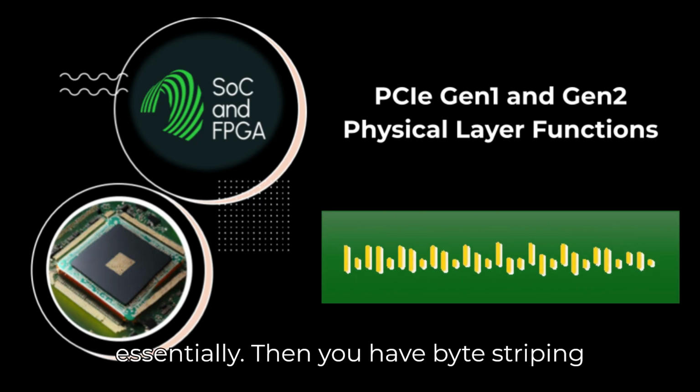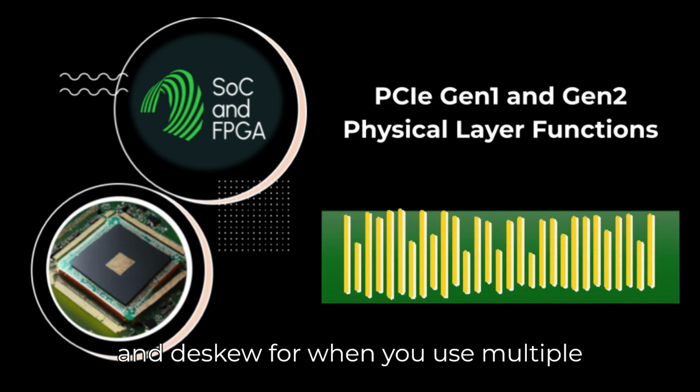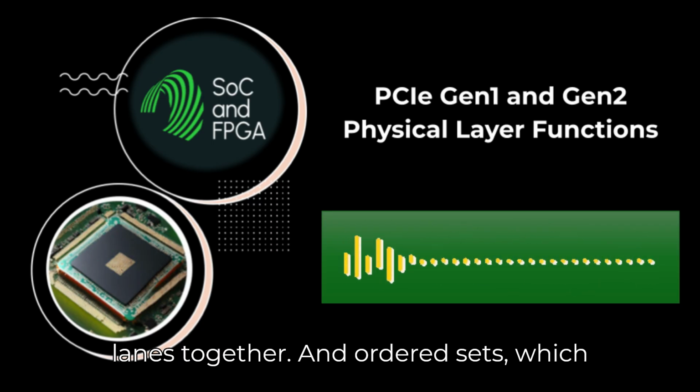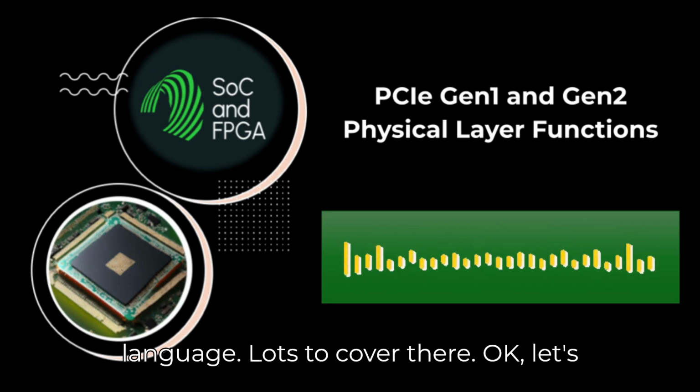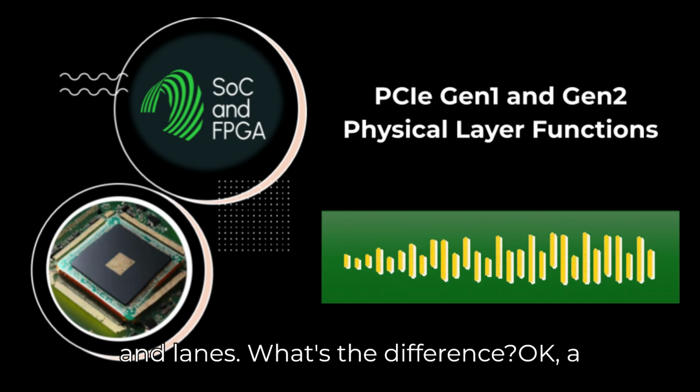Reduces electrical noise, essentially. Then you have byte striping and deskew for when you use multiple lanes together, and ordered sets, which are like the PHY's own private command language. Lots to cover there. Okay, let's start with the connection itself. Links and lanes, what's the difference?